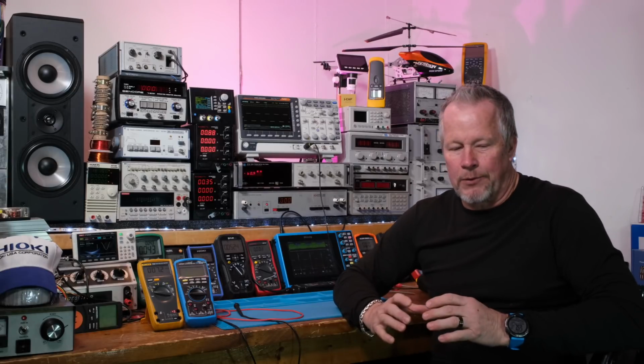If you defeat that prong, then that prong itself is going to have some voltage on it, and if there's any metal that you can access somehow, it's going to have some voltage on it. But that prong all by itself just hanging out there in the breeze, if it's not plugged into something, is going to have some voltage on it, and that's potentially dangerous. So if you've got a plastic box, there's nothing to tie the earth ground to, and so you don't really need it.